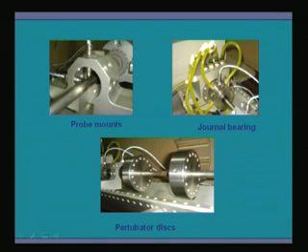These are proximity sensors. There is a gap between these sensors and the shaft, and when the shaft has some displacement, they give the displacements in the horizontal direction and the vertical direction. There is a fluid film bearing. You can see various taps through which we can measure the pressure variation along the circumference of the bearing. These are the displacement probes which are measuring the displacement of the bearing.